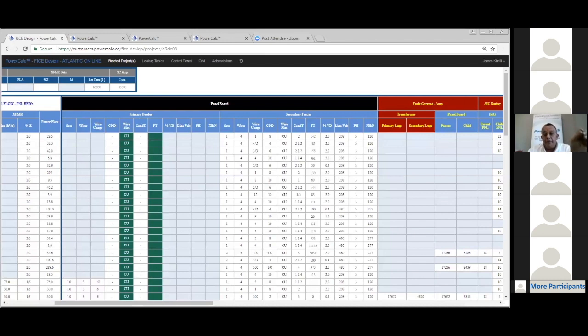of the feeder. Okay. Now, the other calculation that we need to perform that will also affect the output of the short circuit calculations and the AIC ratings of the panels would be the voltage drop. Why the voltage drop needs to be performed, especially on the feeders, because, as I said, the fault current is sensitive to the distance and the type or the size of the conductor.